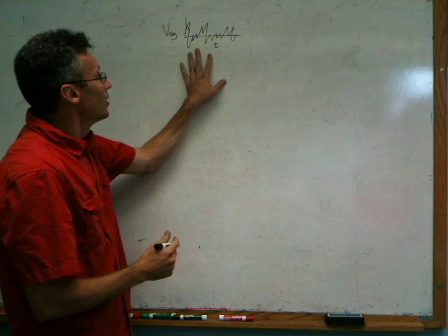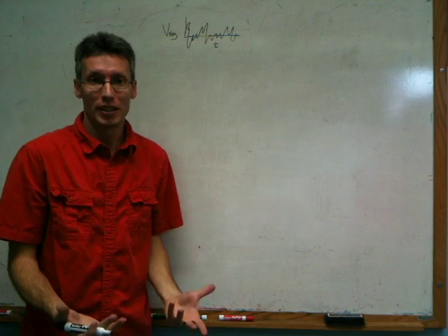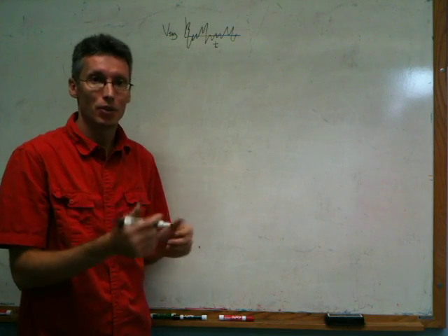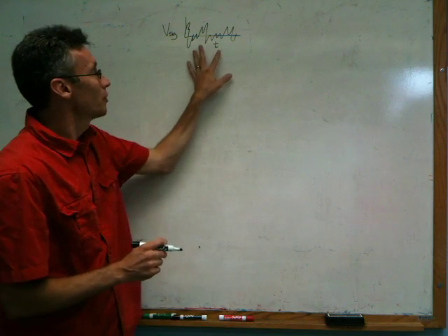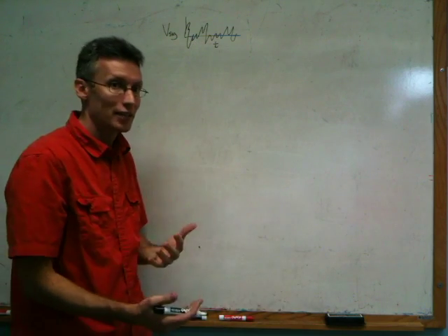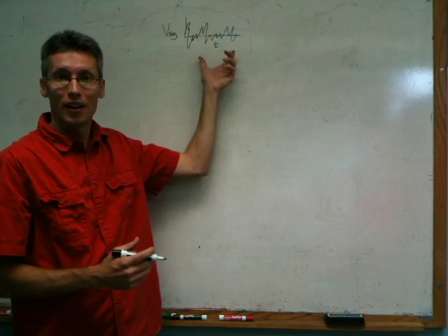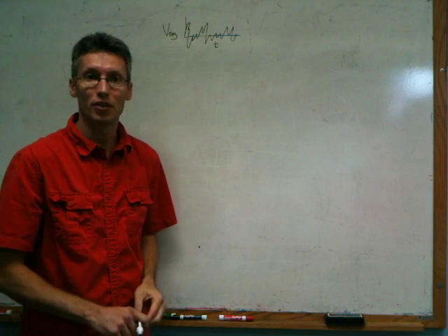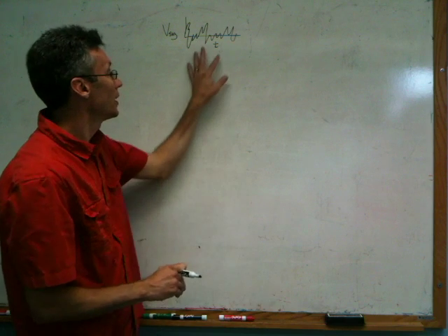So that signal is one of many that are going to be transmitted over the air. And we want the listener to be able to choose which station they're listening to. And we wouldn't want to just simply broadcast this signal directly for a variety of reasons. One is that the frequencies at which the signal are at are not ones that are particularly conducive to small antennas that you might have in a car or on a radio.